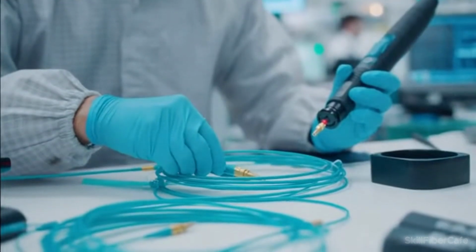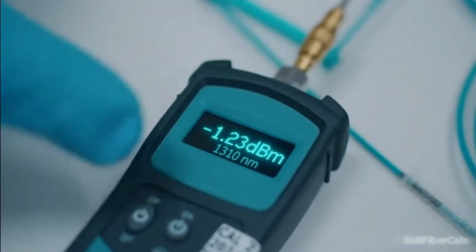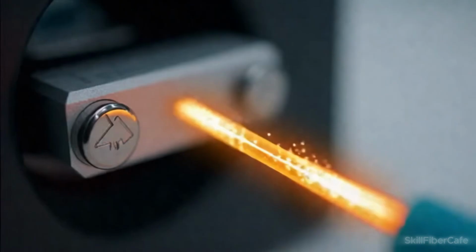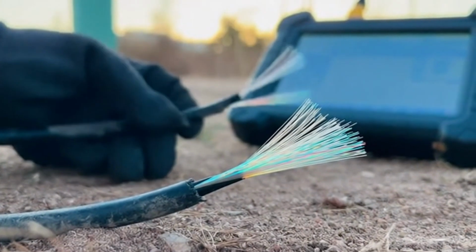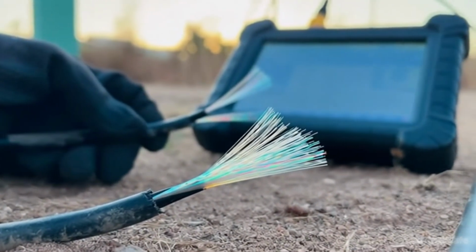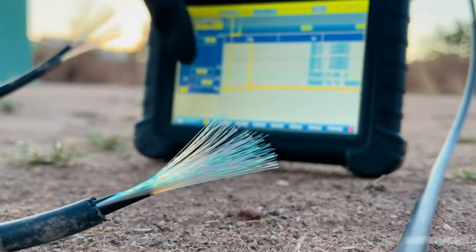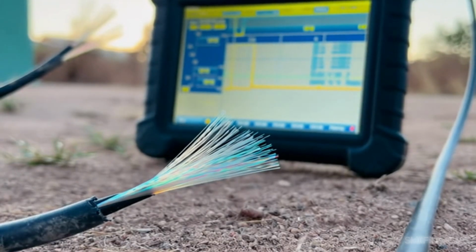Fiber testing ensures design compliance. OTDR pinpoints faults and measures attenuation along the link. OPM or OLTS verify end-to-end power loss against allowed thresholds: 0.3 to 0.5 dB per splice, plus 0.75 dB per connector, plus 0.35 dB per km distance. VFL uses visible red light to trace fibers and detect breaks or bends, allowing rapid field diagnostics and certification.